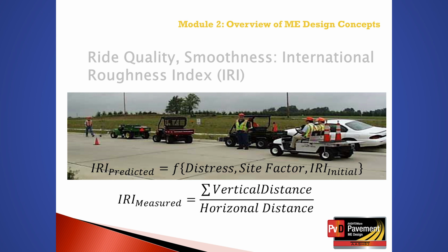And while distress is a measure of structural condition, ride quality is a measure of functional condition. And it is a parallel to the well-accepted serviceability to performance relationship derived from the original AASHO road test.